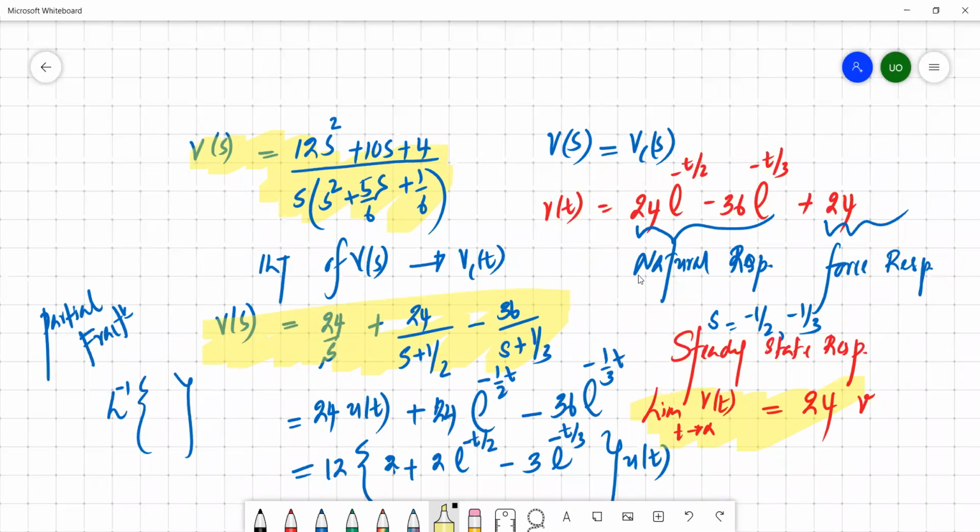If you are asked to do it in the time domain, you have to follow these time domain approaches, get the differential equation and characteristic function, and follow the steps we discussed previously. If it is not specified, or if you are asked to apply the Laplace transform, just convert this time domain circuit into a Laplace or S domain circuit, solve it in S parameters, get the result, and convert it back to the time domain by applying the inverse Laplace transform.